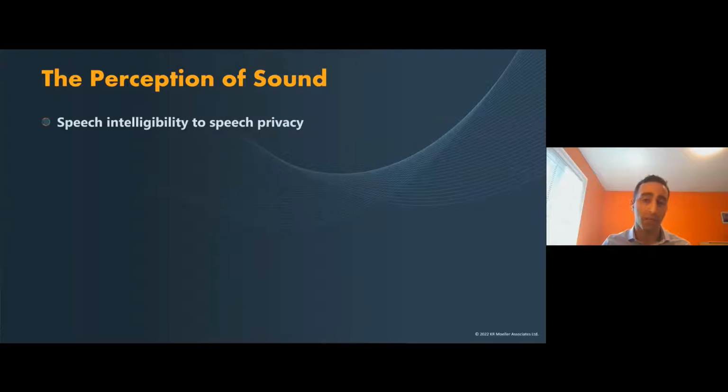To adapt the masking effect in speech intelligibility theory to the built environment, acousticians considered its inverse. That is, the degree to which speech became unintelligible between two positions in space. As speech becomes less distracting, disturbing, annoying, intelligible, or audible, we essentially have a greater degree of privacy. Now, you may be wondering why we're leading into a conversation about speech privacy, because many people believe the concept is a niche application, one more relevant to corporate, government, healthcare, and higher security environments. There are at least two reasons why.